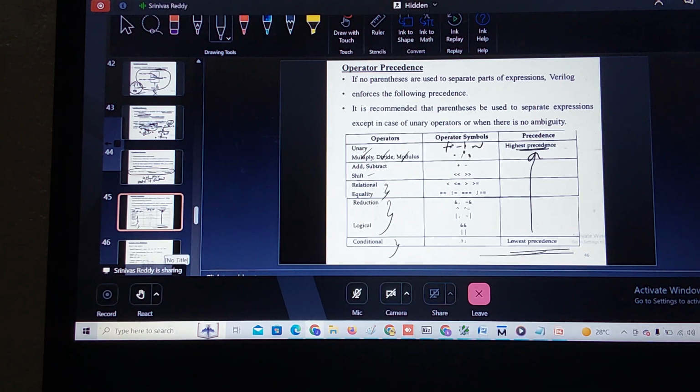always the left hand side of the assignment, it may be scalar or vector. The right hand side should be what? It should be a range or a scalar or net data. Scalar, vector, it may be net data type or range data type. It is continuously assigning. So it is computing at the right side and that will be continuously assigned to the left hand side so that it is in active mode. Continuous assignment statement is nothing but an active mode.